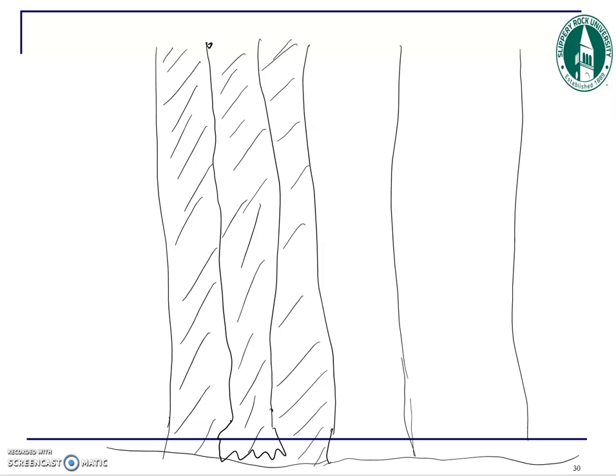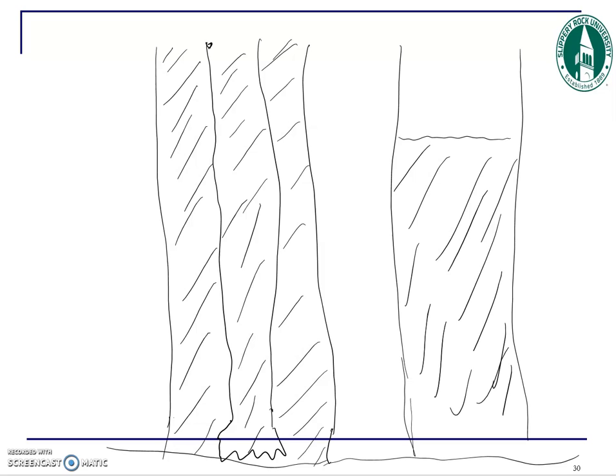What happens to the level of drilling fluid inside your wellbore? It drops, right? Why? Because you had some strings which had some thickness here, and you had a drill bit, and you removed them. Now that part is filled with drilling fluid, so the total level of drilling fluid inside your wellbore drops.